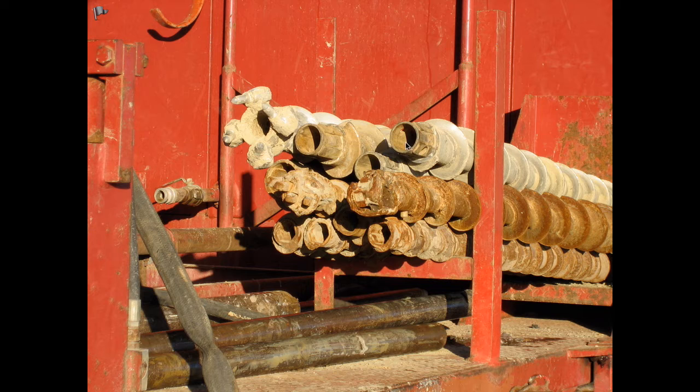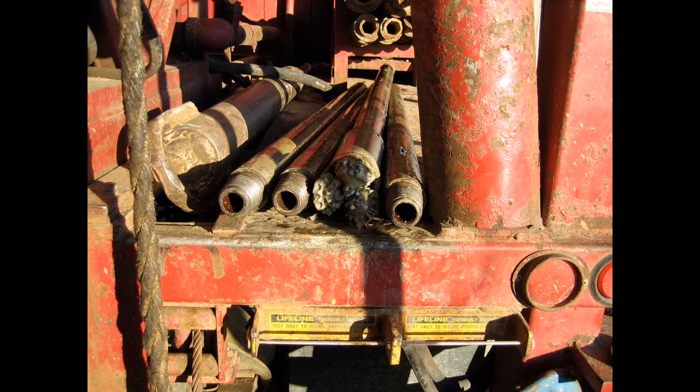So this is a male joint that goes into this, and then a pin goes across that. The reason I think it's solid stem is because, of course, if you have a pin that goes across this, you can't have something that goes down through that pin to take out the central part. And so these are a series of solid stem augers on the side.